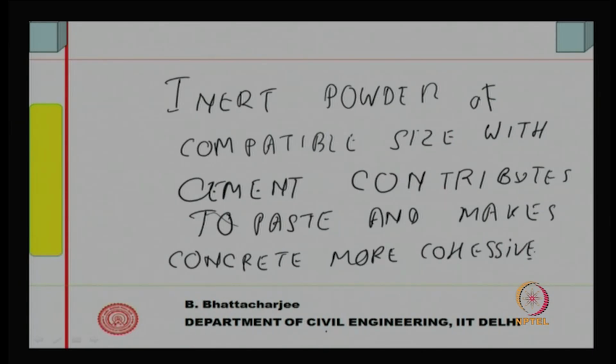If it is a pozzolanic material, then also, because of their sizes which are compatible with the cement or nearly cement size, they can pack well within the cement system. Therefore, they also contribute to the paste. Now, in modern types of concrete, this has high relevance. For example, pumpable concrete, where you want more cohesion, the slump required would be of the order of 120 or 150 millimeter.